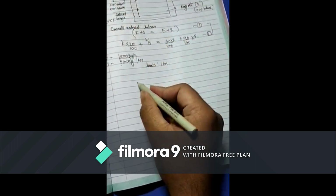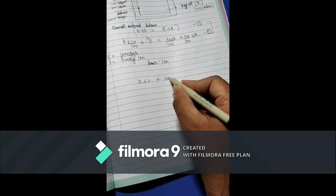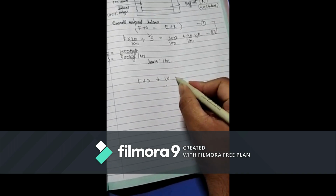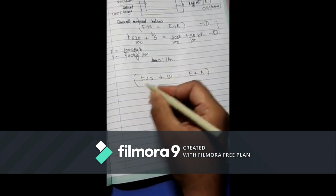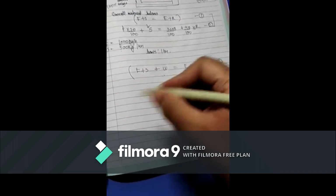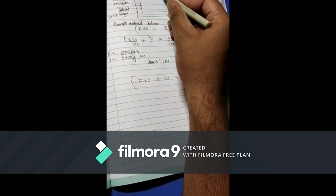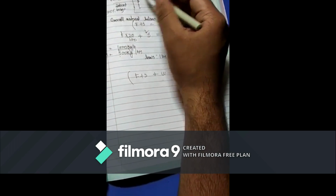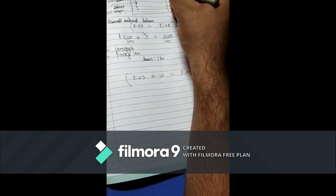So then your equation will become feed plus solvent plus W, which is water removed by the evaporator, is equal to extract plus raffinate, right? Now you can again apply material balance on toluene, but think this: the evaporator will only remove water. It won't remove toluene. So the concentration of toluene in the evaporator stream is 0%.